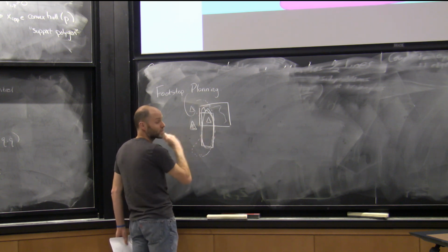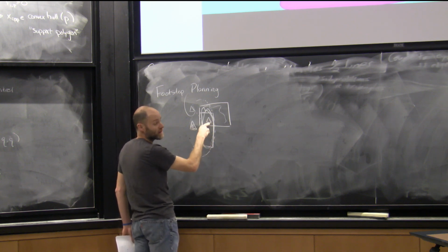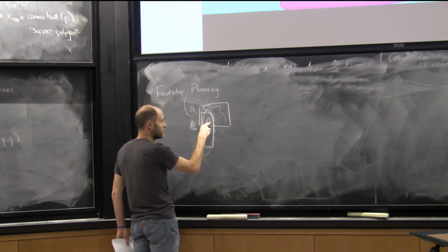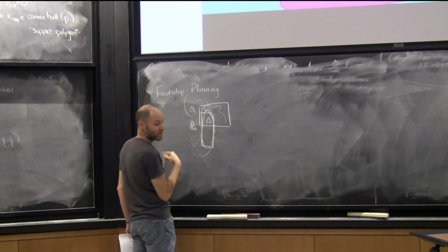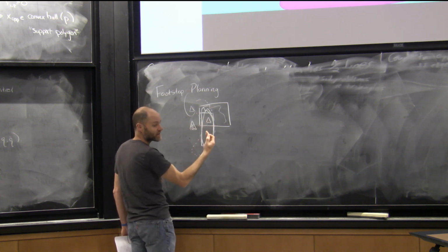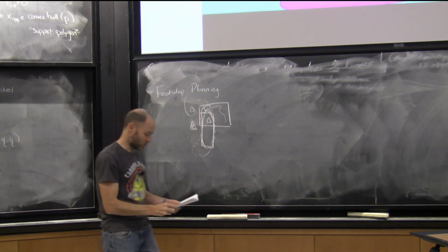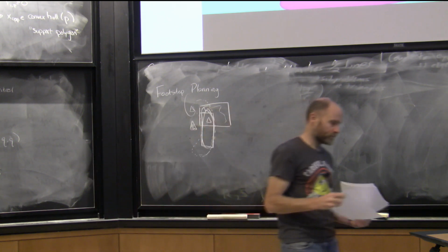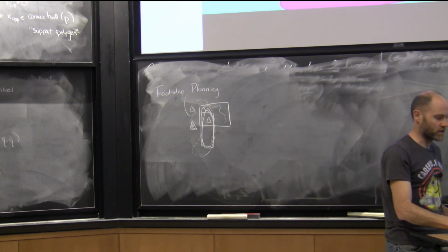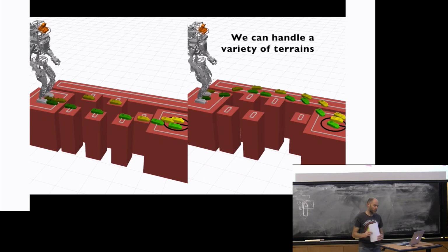We did a nonlinear optimization to begin with, and we ended up with a mixed integer optimization where we explicitly had the assignment of foot to region as an integer variable in our optimization, and we used a mixed-integer convex solver to plan our footsteps. And that actually works very well, up to the conservatism of those approximations, right? So that was the thing I showed you quickly last time.